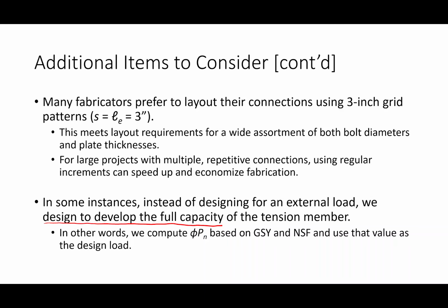If you asked me to design a connection and didn't give me any knowledge about what loads it was going to see, like a brace in a building where you don't tell me the loads or the bolt spacing you'd like, I would probably just use 3-inch spacing and design to develop full capacity. The downside is that the connection is a little bit over-designed, but the upside is it's not going to fail. So it's something worth mentioning.